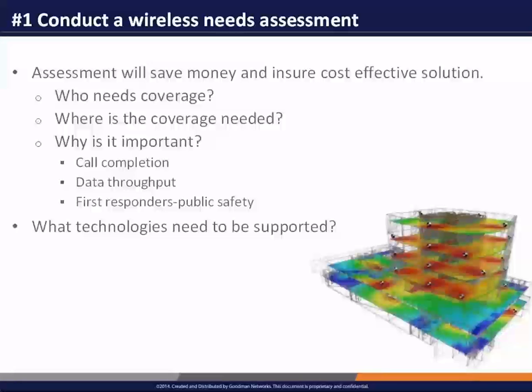At the same time, you need to talk to your first response people, your campus police and security, and understand what the system means to them. How is their systems working now? And how can you integrate the DAS system into first response radio? This is frequently overlooked, but it's critical because you have an opportunity when you install a DAS system to piggyback public safety support onto that system, and at the same time meet some ordinance requirements that may require you in the near future to validate that the systems are going to be working and will support police and fire radio